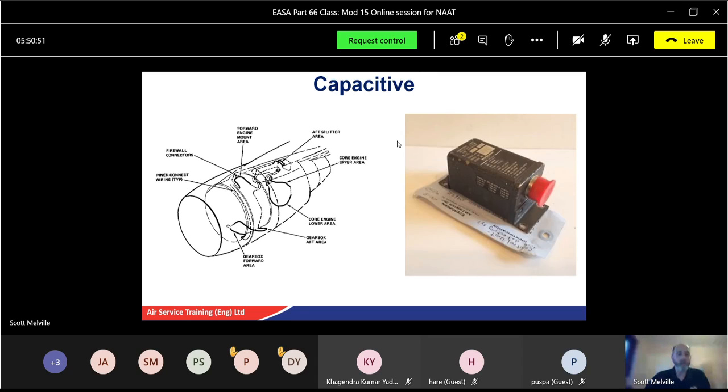The element is then polarized by applying a half-wave rectified AC from the control unit, way back to module 3 stuff, and stores it. As it stores it, it discharges it as a feedback current to what's called a silicon controlled rectifier in the control unit during the non-charging half cycles. Way more in depth you need to know, but that's just how it works.